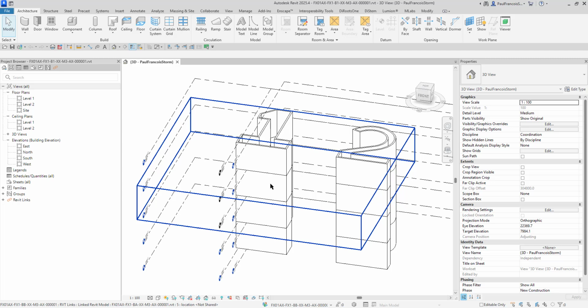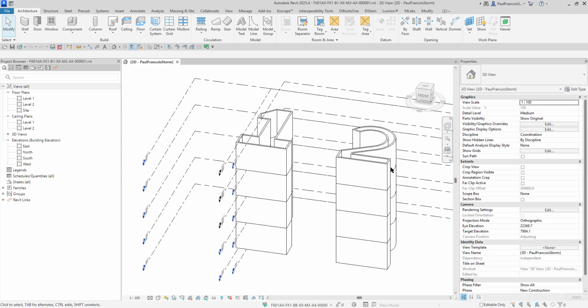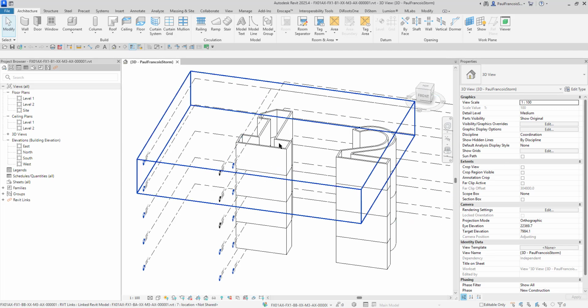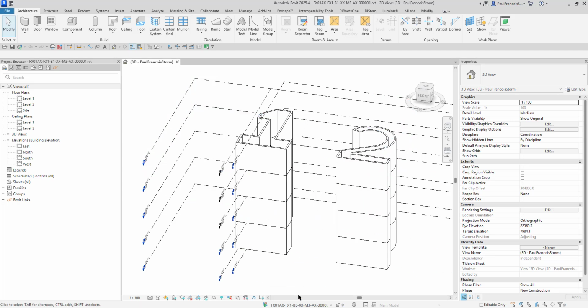It's going to be used on multiple floors and various different orientations within a building, all with the same layout. In other words, any typical room. Now, there is some discussion in the industry, should you use that as a link until you've locked the design down, in which case you can bind the links and start populating the data for things like the door numbers, or should you use groups?